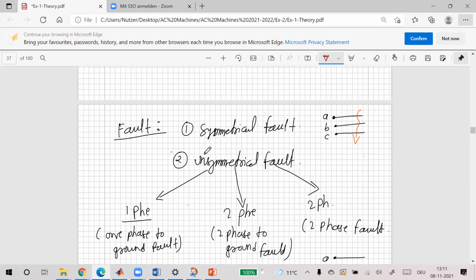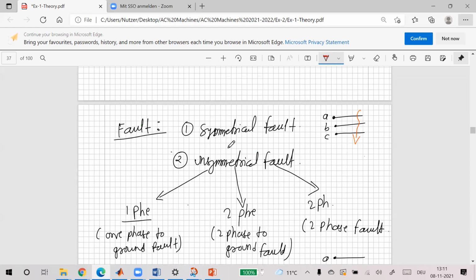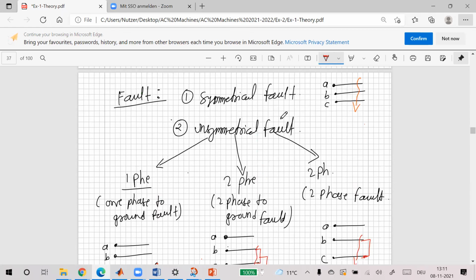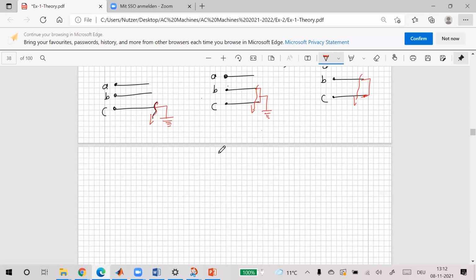Now you would like to see the transformations during the faulty conditions. So when you have a symmetrical fault, you would see your voltage will dip. Basically, all your DQ voltages will dip because there is no magnitude for the voltages. But in unsymmetrical faults, we would see some unusual things in the alpha beta frame.